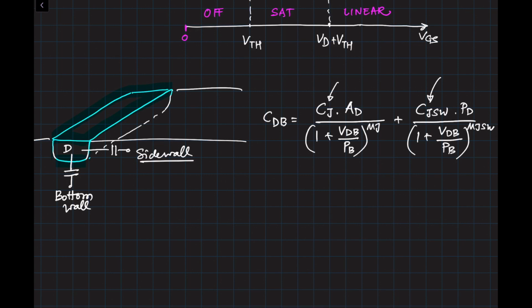So this is how you model the transistor with a whole bunch of different types of capacitances, and the insight about where they are coming from. What we have to know as circuit designers is we should be able to figure out which capacitances to keep and which capacitances to ignore. That's the insight I'm going to teach you, because otherwise the circuit looks very complicated.